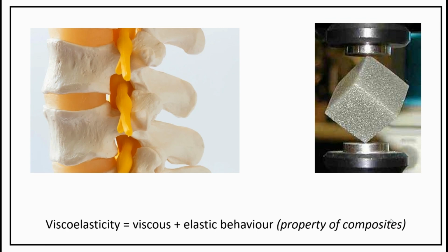Viscoelasticity is a combination of viscous and elastic behavior. It is a property of some composite materials which makes them exhibit both viscous and elastic behavior. These materials are capable of undergoing deformation under tensile or compressive forces, and although they return to their original state after removal of the force, the viscous qualities make the deformation and return time dependent.